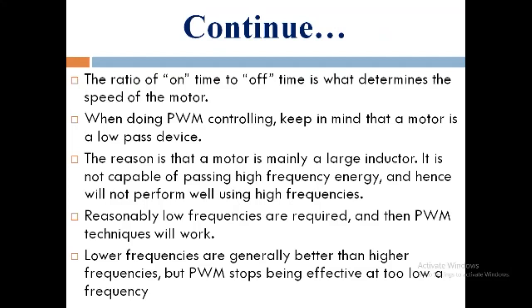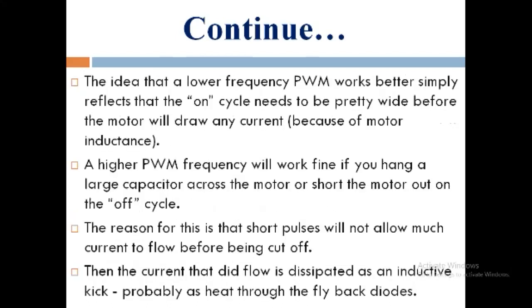Lower frequencies are generally better than higher frequencies, but PWM stops being effective at too low a frequency. The idea that a lower frequency PWM works better simply reflects that the on cycle needs to be pretty wide before the motor will draw any current because of motor inductance.